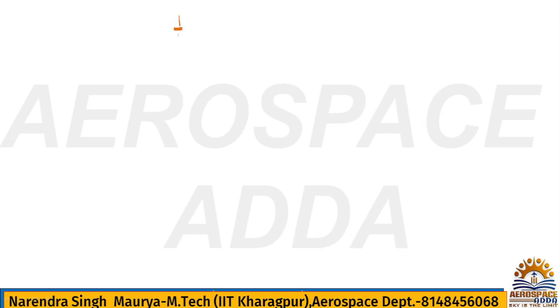First you will write for the true air speed. What is the dynamic pressure? Half rho v square. This is for true air speed, so true air speed and density will be at the same altitude, 4 km. This dynamic pressure must be equal to half rho v square for equivalent air speed, hence your density will be sea level density.